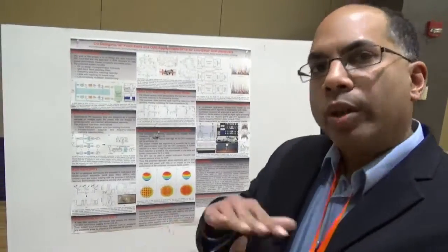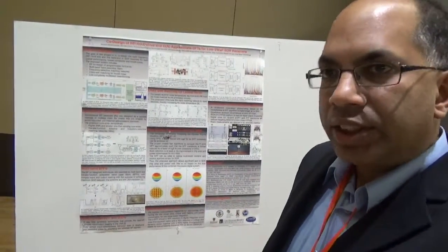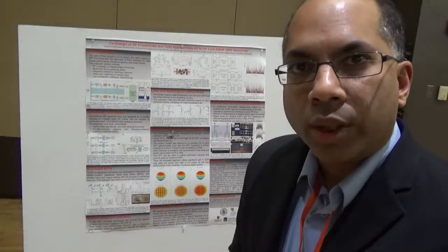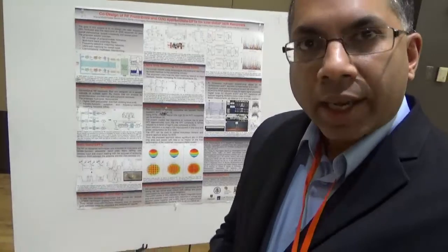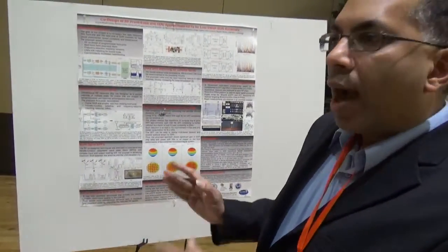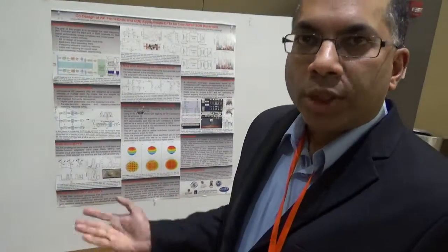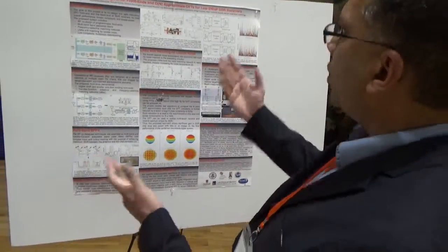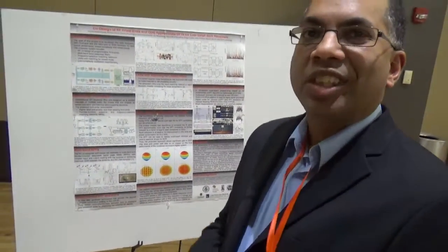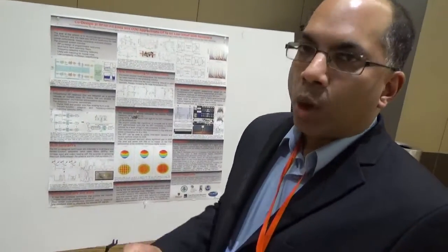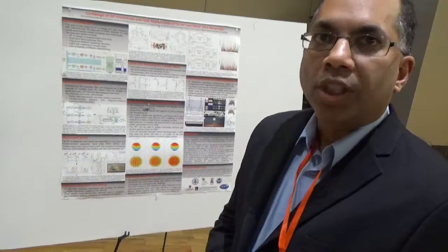Once we know the best we could get from this transceiver, the analog part, we can go back to the software-defined radio algorithm and allow just the right amount of error so that you can get the best power consumption and complexity in the digital part while not getting any hit in the performance of the total system. So that's a broad optimization using order n complexity approximations of the discrete Fourier transform to get overall lowest power consumption and chip area without much hit in the performance of the total system. Thank you very much.